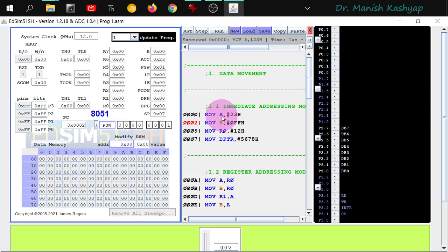Then, similar to this instruction, you can also move data into the B register. The syntax that you follow for FF, or any number that begins with a non-numeric digit, is that you have to put a 0 before that number. Mind that 0 is typed as phi in this particular font, so you will press 0 but it will look like this.